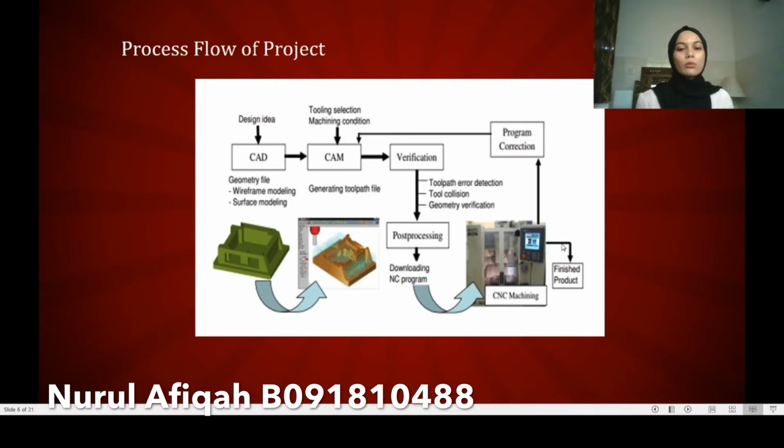After that, we move to the verification process, where we analyze the toolpath error detection and tool collision, which can happen sometimes. We can analyze at this process, and it also comes with the geometry verification.